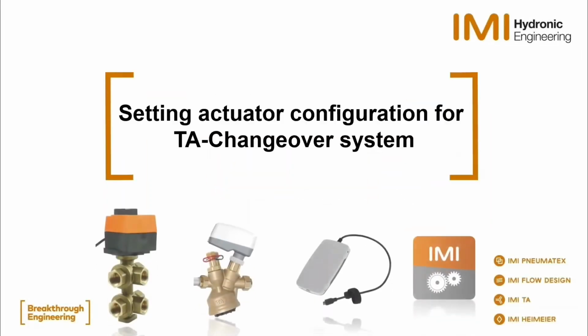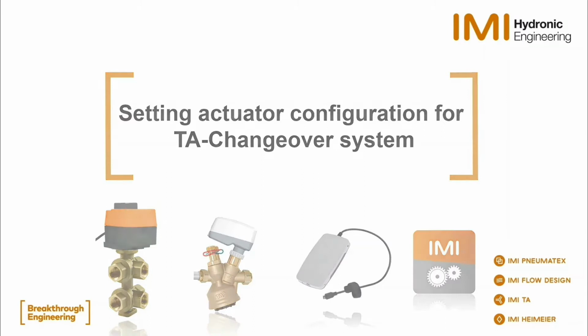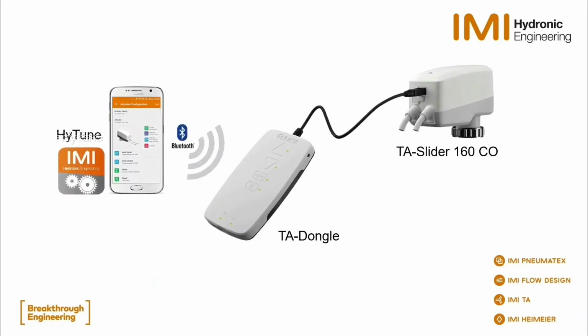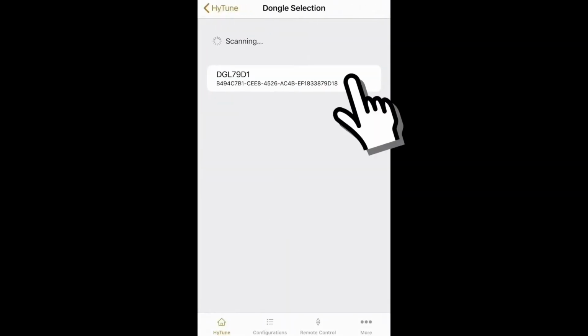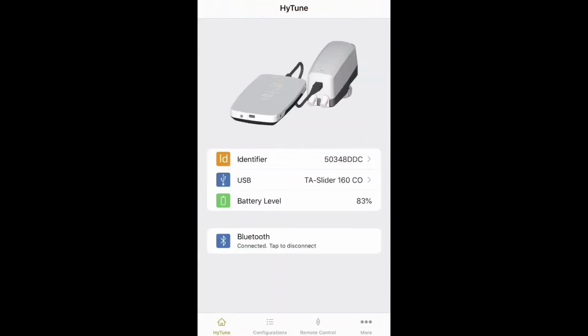The TA dongle provides you the ability of setting the actuator configuration for the TA-Changeover system using live configuration or offline configuration. For live configuration of the actuator, connect the TA dongle to the TA slider actuator using the wire provided on the dongle. Then open the HiTune app, go to Bluetooth and connect to the TA dongle. You should be able to communicate with both TA dongle and the actuator with your smartphone.